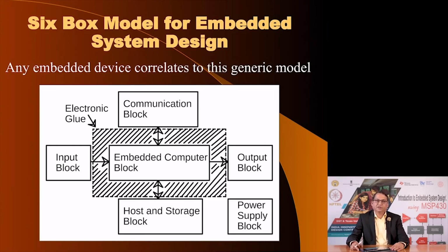Most embedded system applications would require at least these 3 blocks and the power supply block, because without power supply it is not possible to run any electronic circuit. Certain embedded applications may also require communicating with the outside world, and so you have a communication block. Sometimes it may require storing data locally beyond the capacity of the microcontroller, so you would have maybe a hard disk or a serial storage device.